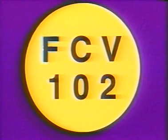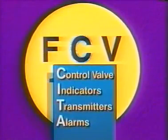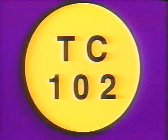The letter symbols for the names of process variables are usually made from the first letter of each name. Here are the letter symbols for the 4 most common process variables. Here are some possible middle letters for instrument symbols. The letter C is used for control valves. The other letters are used with indicators, transmitters, and alarms. If a controller is a blind controller, there is usually no middle letter in the symbol. For example, this symbol indicates a temperature controller that doesn't record or indicate.